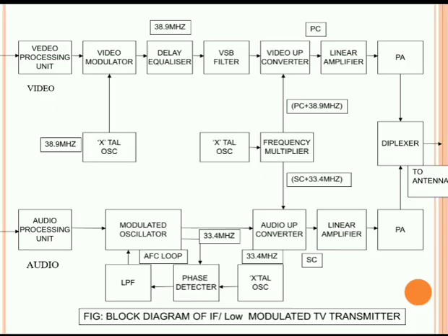So in that particular diode balance modulator, the amplitude of the signal is modulated, and the harmonics are also removed by using the filter. In the diode balanced modulator, we get the AM modulated signal along with the harmonics. Harmonics are then eliminated by using the filters. The phase compensator or delay equalizer is built in with the VSB filter to compensate the phase distortions here.